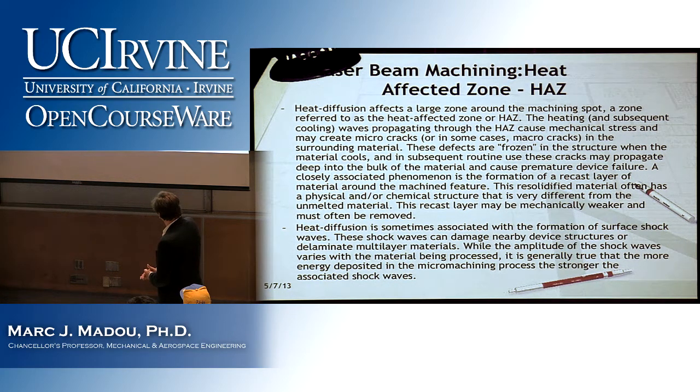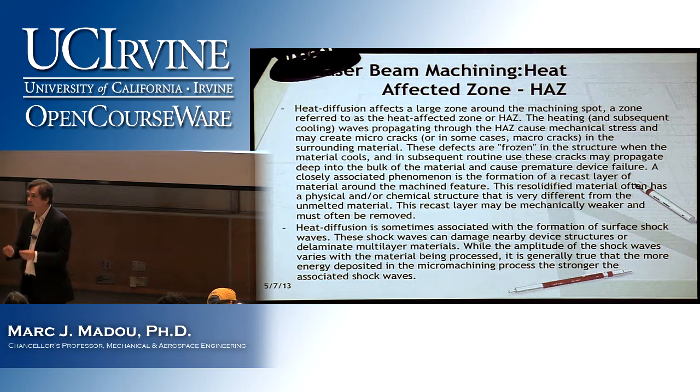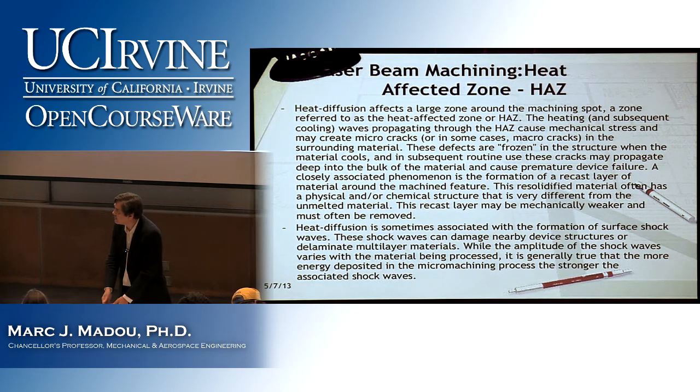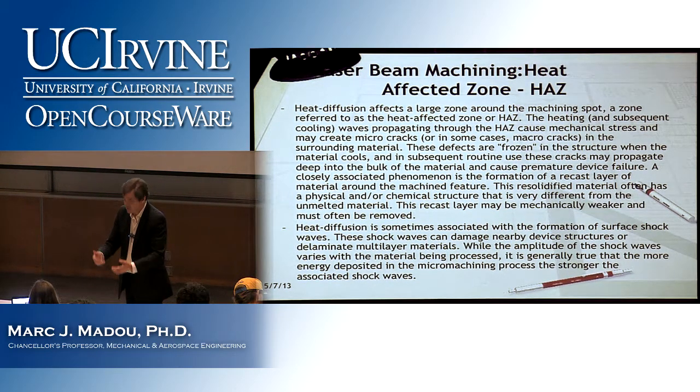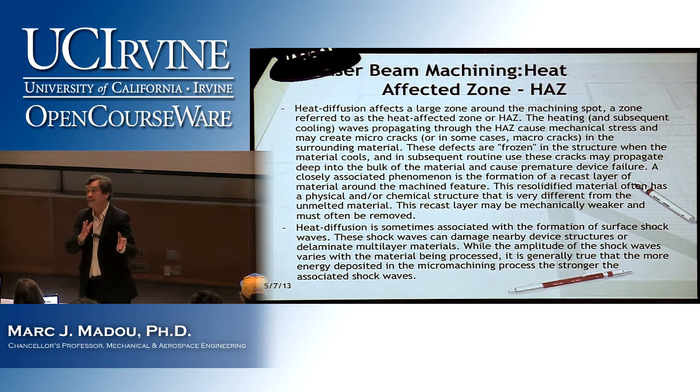It's not only heat diffusing out of the spot where you machine, you also have material that redeposits. It's literally like melting so violently that you will have some splashes of metal, or even ceramic, splashing out of the hole you're drilling with your laser and basically causing a recast layer. Again, quite undesirable.